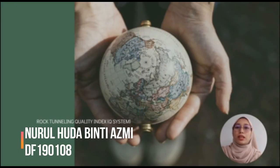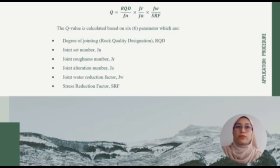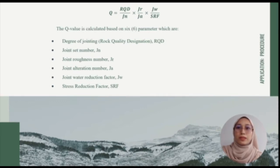Today I will be presenting to you about the application of the Q system. To find the Q value of the Q system, there are 6 parameters that we need to determine. The Q value equation is Q equals RQD per Jn times Jr per Ja times Jw per SRF. The Q value is calculated based on 6 parameters: first is the rock quality designation RQD, joint set number Jn, joint roughness number Jr, joint alteration number Ja, joint water reduction factor Jw, and the last one is the stress reduction factor SRF.